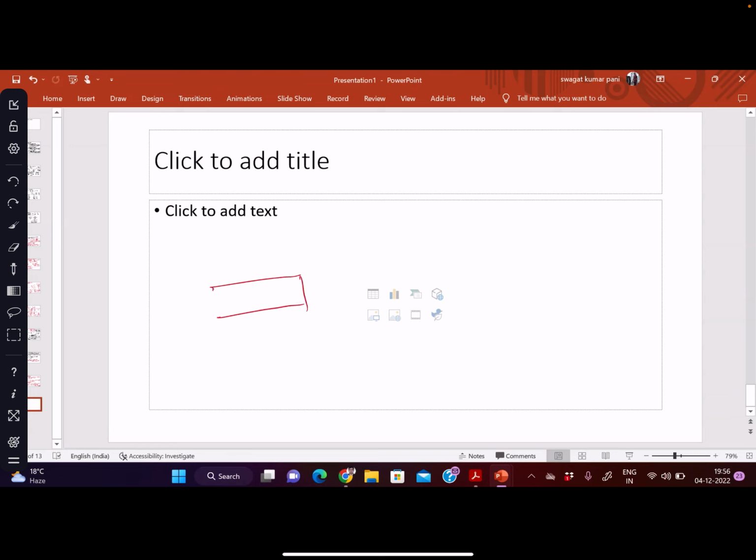Suppose we have a sample with vacancies here and we are loading in this direction. They will coalesce and form a void. So now in this region the area is A0, and in this region the area is reduced, A is less than A0. So the stress will increase, because we know stress equals load by area. If the area is small, the stress will be higher in this region. So this region will start deforming more.